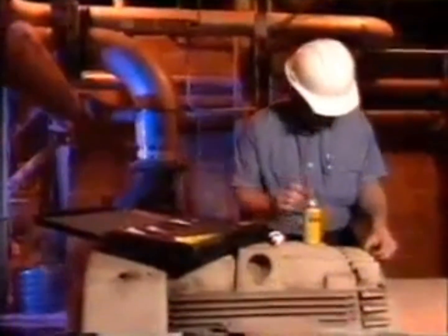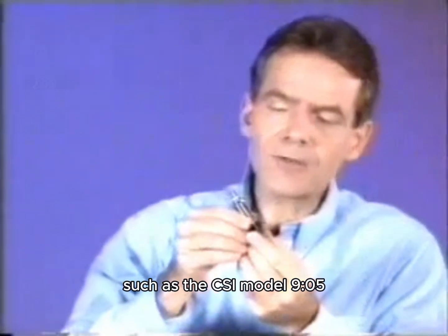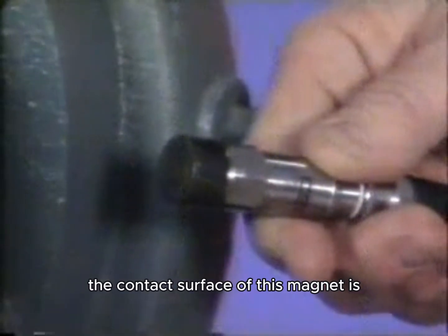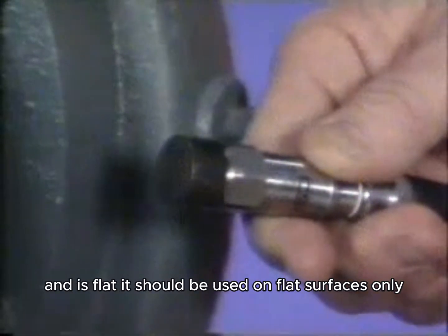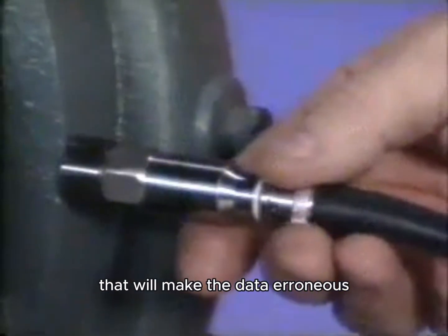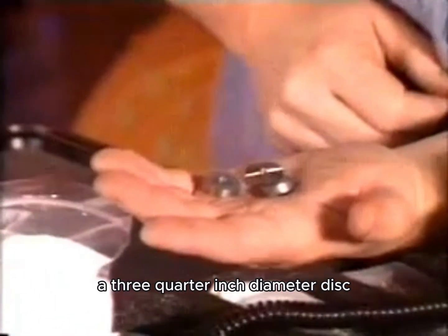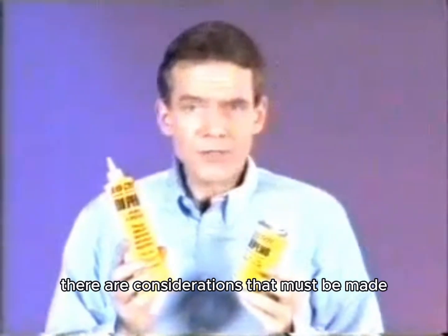When using the sensor with a smaller round magnet, such as the CSI Model 905A rare earth magnet, other considerations must be made. The contact surface of this magnet is approximately 3/4 inch in diameter and is flat. It should be used on flat surfaces only to avoid rocking motions that will make the data erroneous. To accommodate the flat finish of the magnet, a 3/4 inch diameter disc could be mounted to the machine surface with adhesive. When selecting an adhesive, there are considerations that must be made.